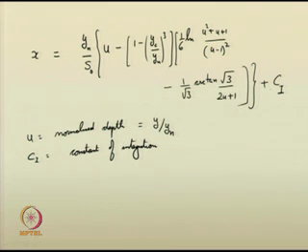All other terms are explained earlier also. So, using this relationship you can obtain the solution for the gradually varied flow profile. From this you can easily determine the horizontal length of the profile, or for a particular depth, what is the corresponding horizontal distance, that can also be identified from this equation.